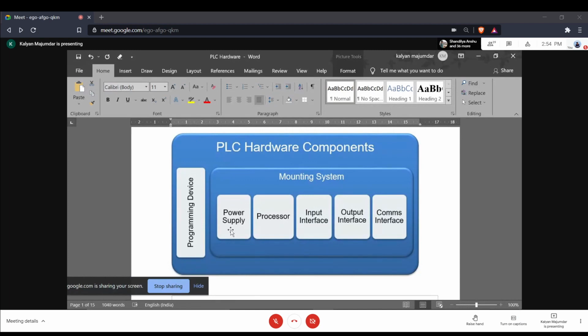Again, use Ethernet, with a switch, again industrial grade, which ultimately connects all these PLCs together so that you can transfer data from one PLC to another PLC, or transfer data to a centralized HMI. That means I have a centralized large screen which takes data from all individual PLCs and provides a centralized display of what is happening where in this particular plant. All information from the plant is displayed at a centralized point.